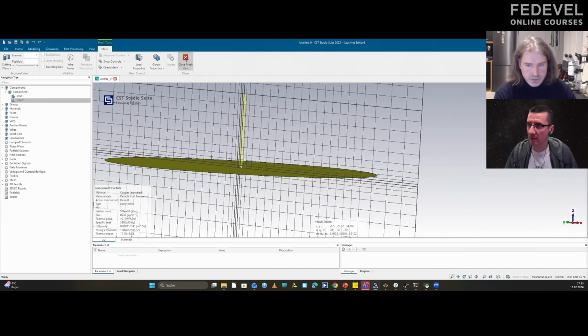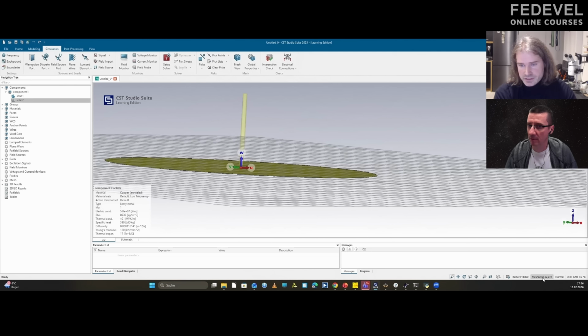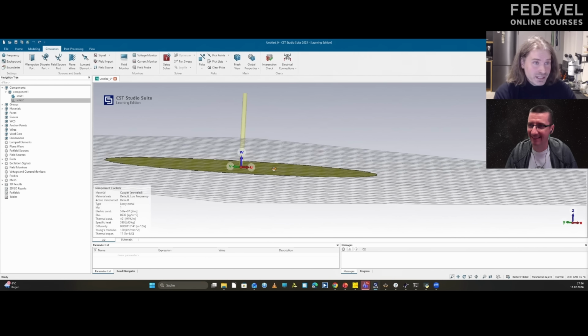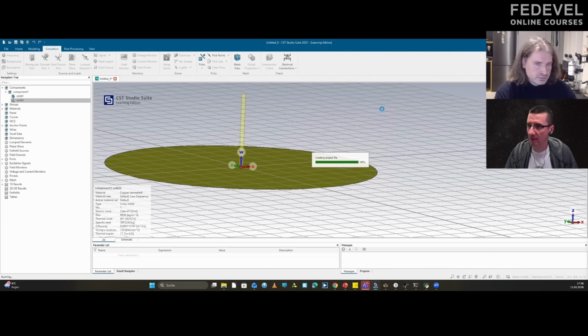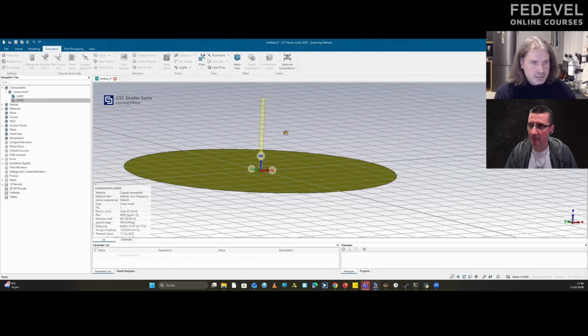So this is okay. We are under 100,000 mesh cells. This is good. If we are above, this wouldn't work. And now we can start with the simulation here. So this is the accuracy. If we go lower, the accuracy gets better because the power is decreasing even lower, but minus 30 is okay. And when we start the simulation, I think it will be very fast here.